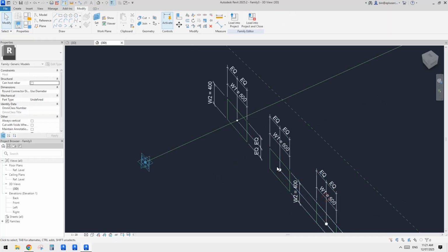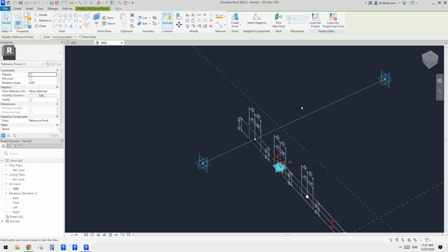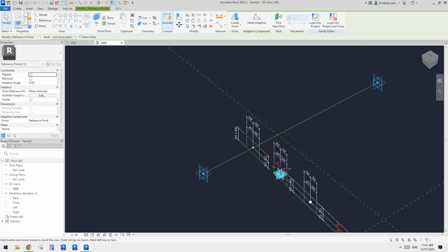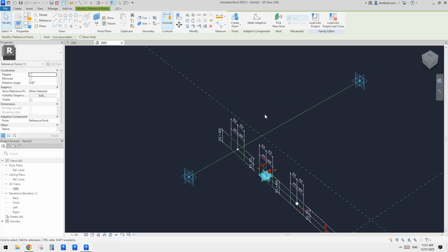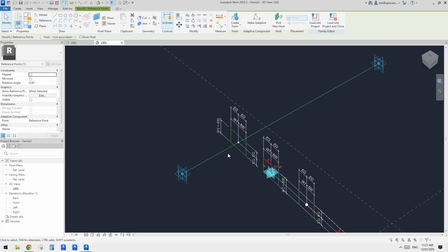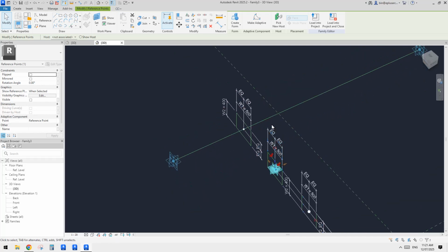Okay, so most of us know that to rotate this one and create a smooth rotation, rather than the one we did previously as a swept blend with only 2 profiles, which creates a straight line edge, we want curved, so we need at least 3.